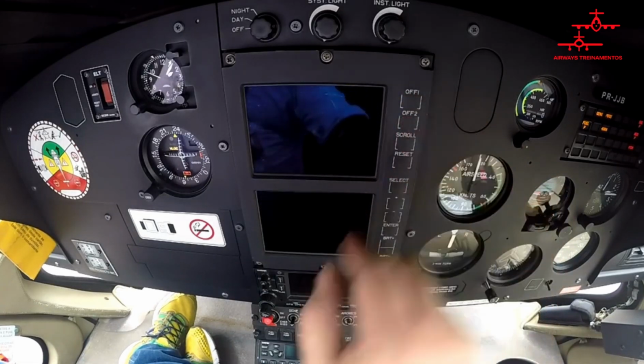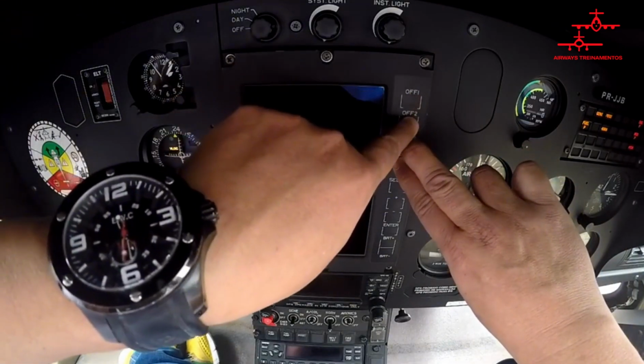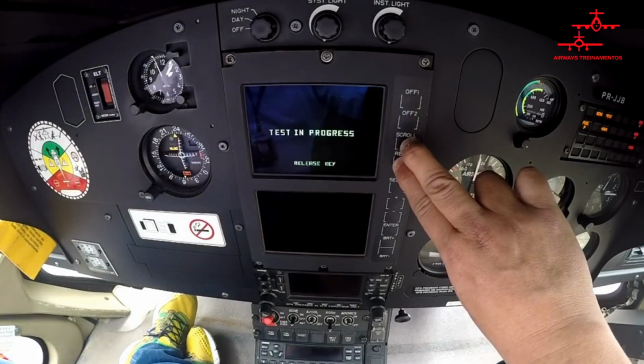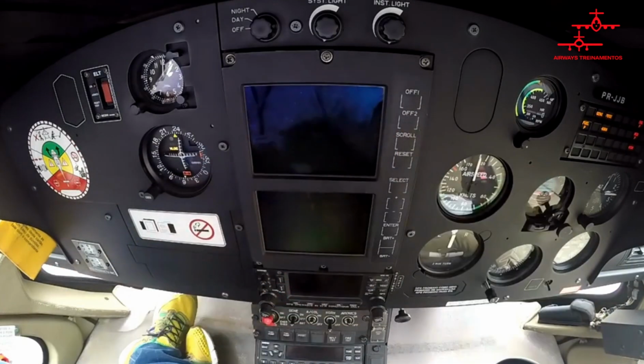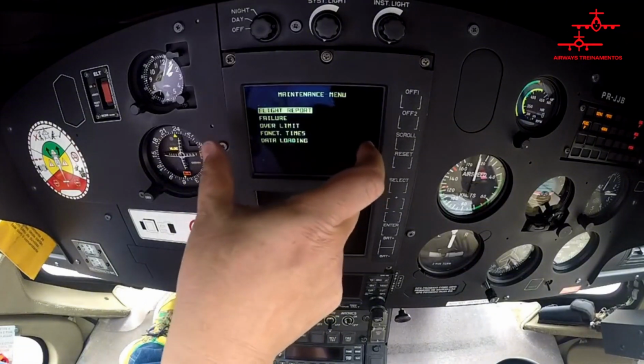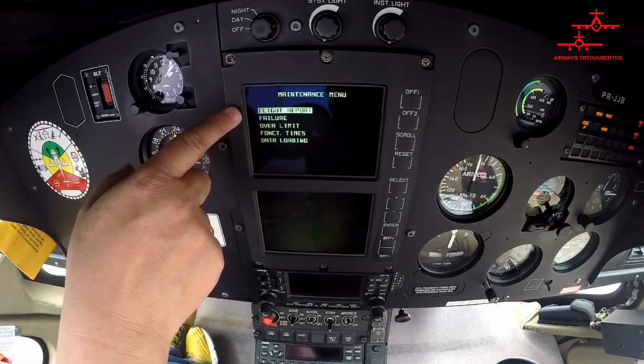I have to turn off both processors, hold scroll and reset, then turn both processors back on. With both processors on, when this message appears, "test in progress, release key," you select it. At this point, I will only have access to the maintenance menu from the top section. The maintenance menu is made up of 5 items.